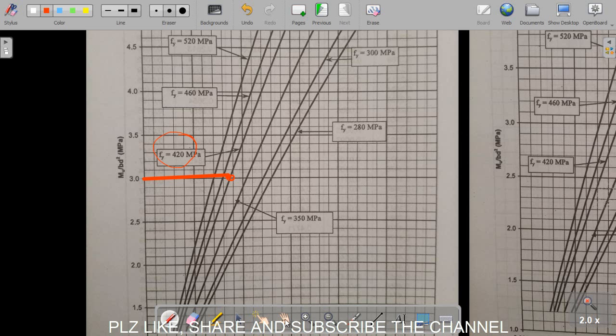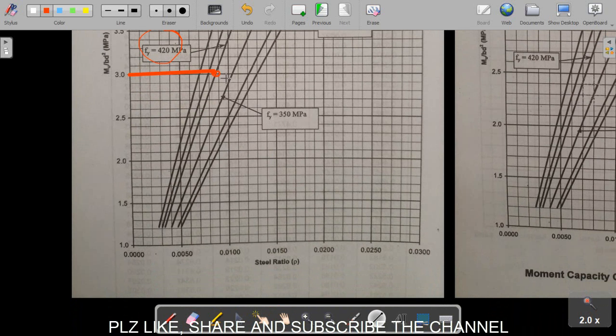Now I will directly extend this point just below, and this is my desired steel ratio, rho, which is around 0.005, and here you can see 0.01. So we will find the value of this point, which is between 0.005 and 0.01.